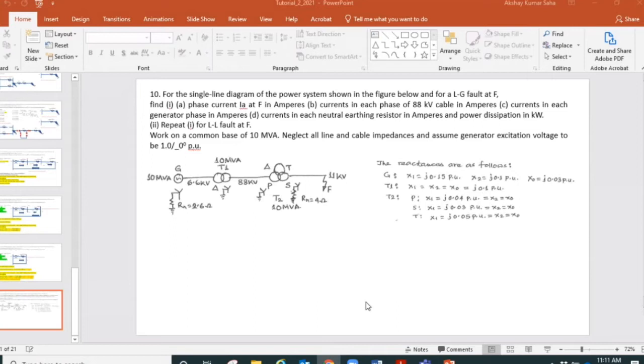Third harmonic voltage, third harmonic current will be flowing there. We don't talk much about the voltage, but third harmonic current will be flowing. We will have to provide a path for the third harmonic current to flow. So for that, we put that delta winding to make a circular path for the third harmonic current to flow in it. That's why we must have a delta.